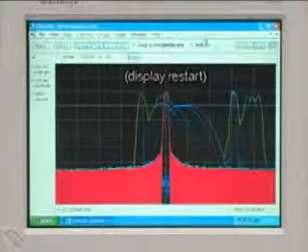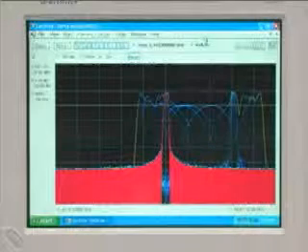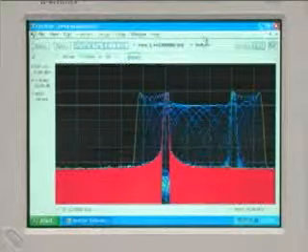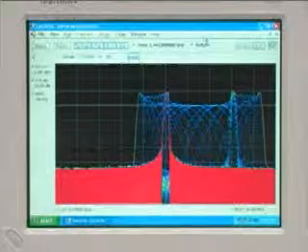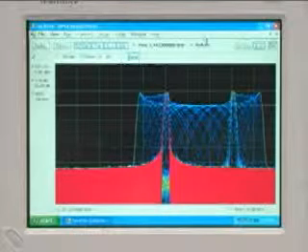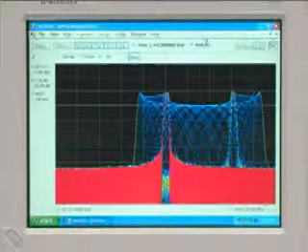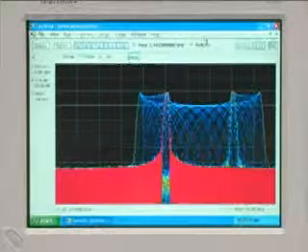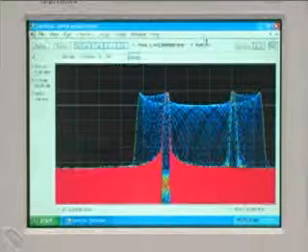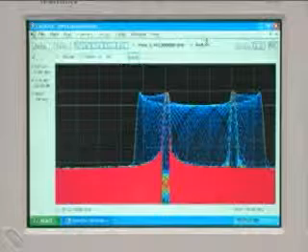The DPX display shows you what it sees in a usable form for the human eye by updating a persistence display 20 to 30 times a second. A persistence display means that every pixel, or frequency and power value, has an associated persistence or intensity value. There is a histogram of data associated with each pixel, and this drives the intensity or color of each pixel.